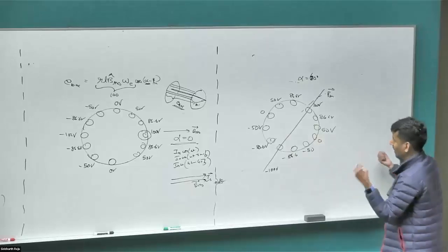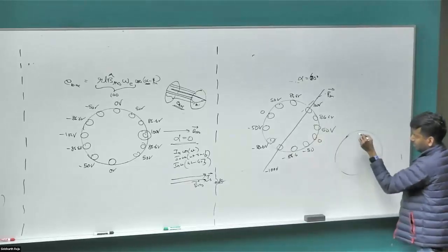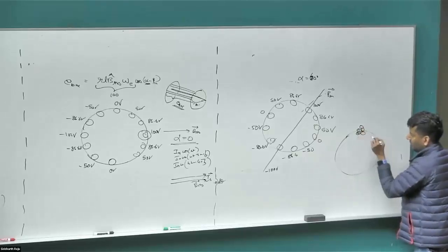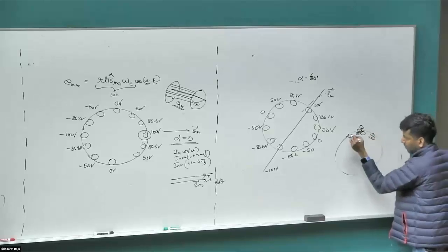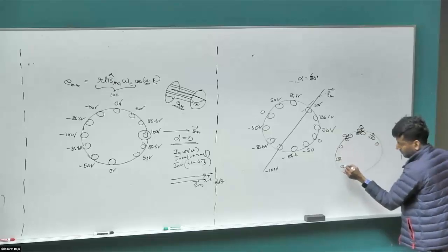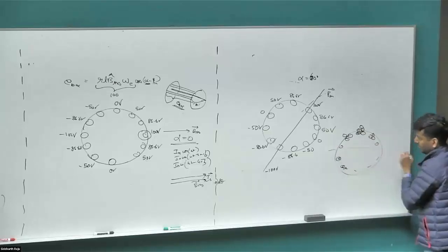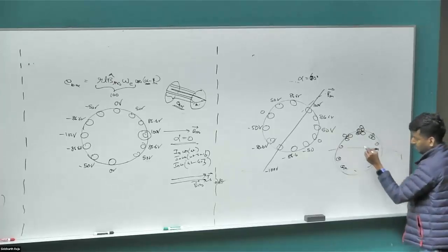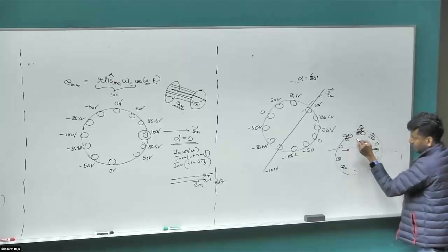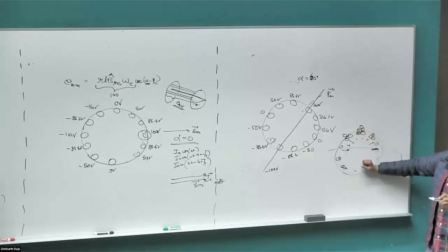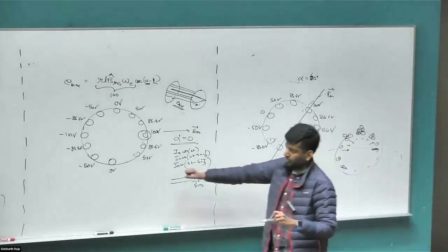So in the case of the stator, we had to do quite a bit of work to get this done. What did we do? We put a bunch of conductors here, and then we reduced the number of conductors going a little bit farther out. And then we reduced it even further. And then the same thing on the other bottom side. Right? So this allowed us to get a B field that was maximum here, negative maxima here, slightly lower here and here, 0 at this point. So this was achieved by distributing the conductor density sinusoidally. And we have already achieved that in the first process itself.